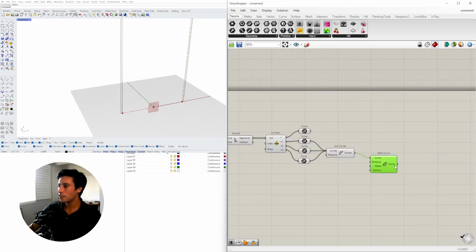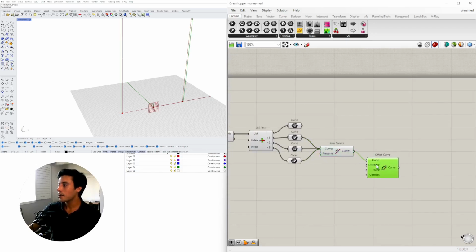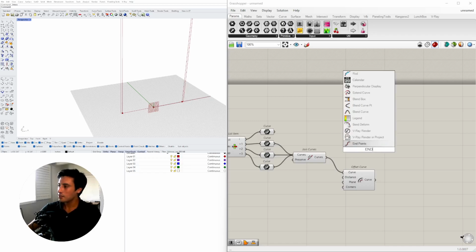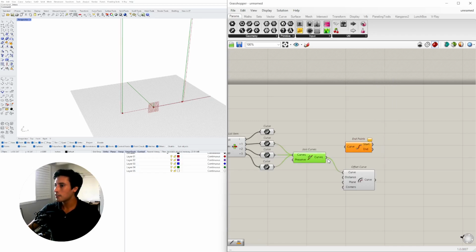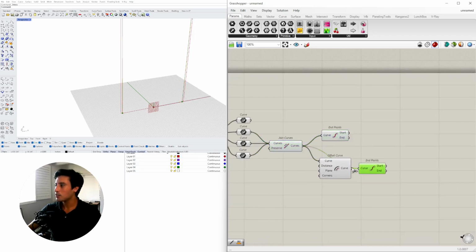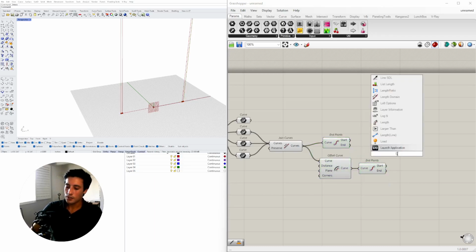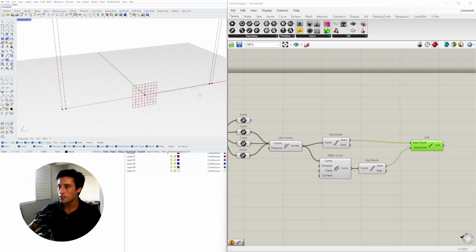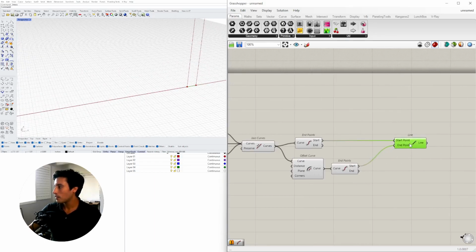Now, we're going to take this offset and this, and we're going to connect them and join them together into a closed polyline. The way I do this technique is just adding endpoints to these lines. So I'll do this one, tap Alt, create the endpoint for this one. And so we'll be connecting endpoints and starting points using line segments. I'll go here to line, from start point to start point, creating this segment, and then copying this and doing the same thing. So slide it down, tap Alt, and we'll be adding these two.